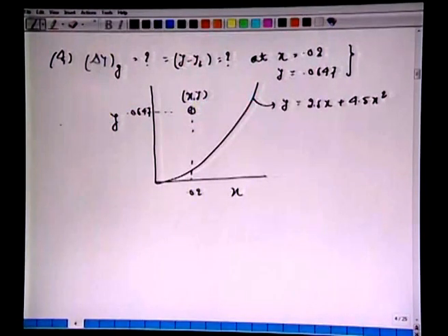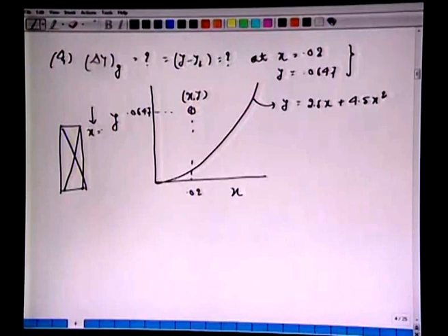In the absorption column, the liquid phase x varies from x equal to 0 to the exit concentration we calculated, which was 0.02588. All right, this was 0.02588, that was capital X1, but we calculated the small x1 as 0.02523.